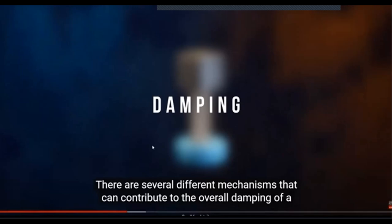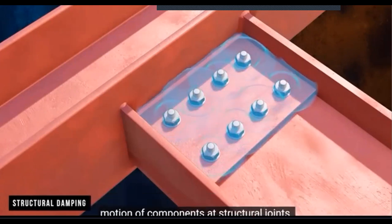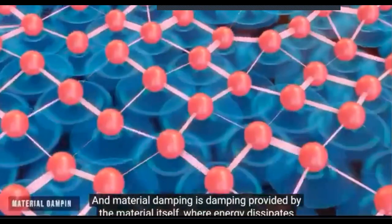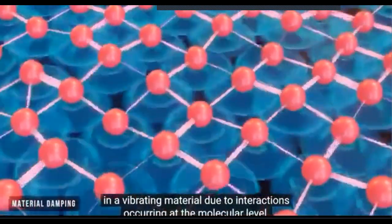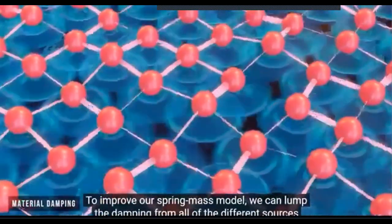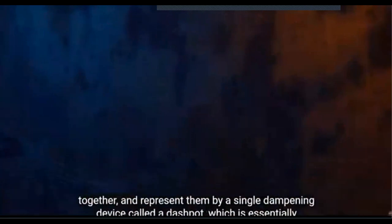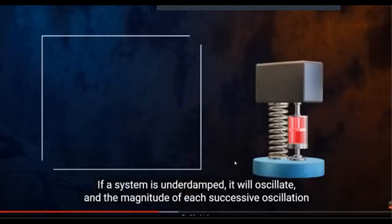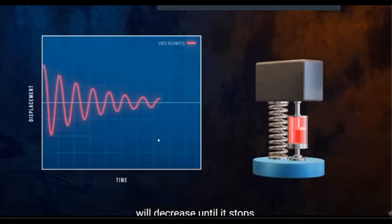That can contribute to the overall damping of a system. With structural damping, energy in a vibrating structure is dissipated due to the relative motion of components at structural joints. And material damping is damping provided by the material itself, where energy dissipates in a vibrating material due to interactions occurring at the molecular level. To improve our spring mass model, we can lump the damping from all of the different sources together and represent them by a single damping device. The system will oscillate, and the magnitude of each successive oscillation will decrease until it stops.